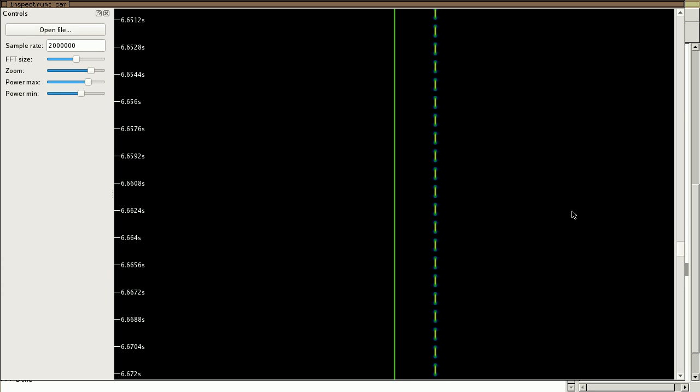Now, this is useful perhaps, but it isn't really showing me what might be wrong with my signal. And I suspect what might be wrong is actually the power level. Do you notice, if I turn up my power max here, do you see how it turns red almost the same point at which this spike in the middle turns red? That indicates that the power level of this received signal is only approximately the power level of this defect here. And that is a little bit troubling.